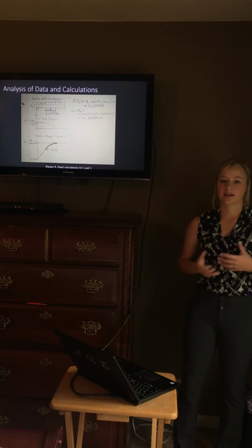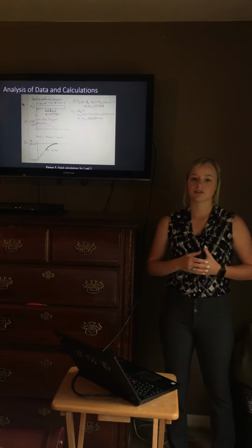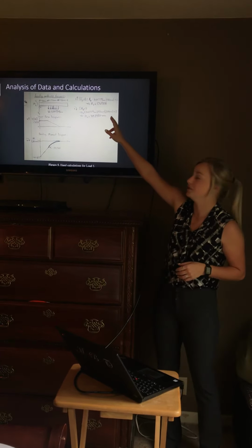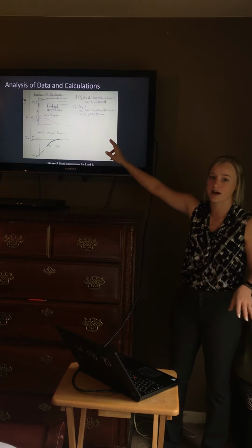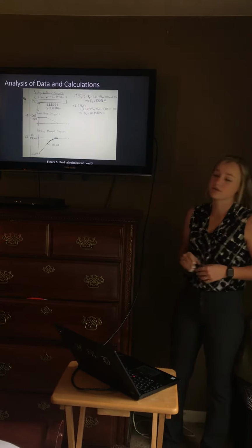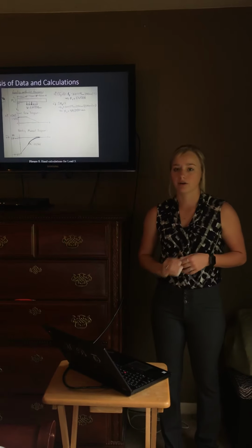So the loading with 6 hangers, same as the previous 2. I do want to note that it did continue to increase. Now we're at 1.7658 newtons for the reaction force in the y direction, and our maximum bending moment was 414.893 Newton millimeters.